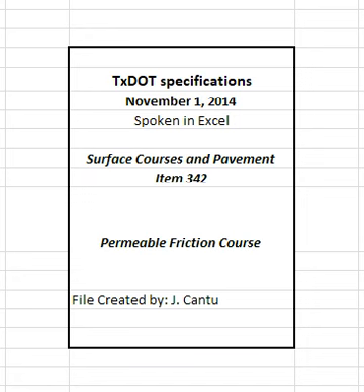4.4 Mixture Design. 4.4.1 Design Requirements. Use the PFC design procedure provided in Tex-204-F, unless otherwise shown on the plans. Design the mixture to meet the requirements listed in Tables 1, 2, and 4. Use a Superpave gyratory compactor, SGC, at 50 gyrations as the design number of gyrations. The engineer will provide the mixture design when shown on the plans.